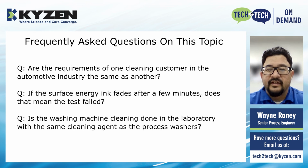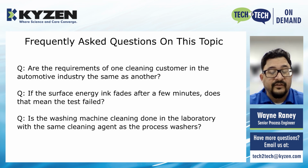Next question is, if the surface energy ink fades after a few minutes, does that mean the test failed? And the answer is no. The ink should remain uniform for at least 2 seconds. After this time, it's normal for the ink to start fading or beading up.